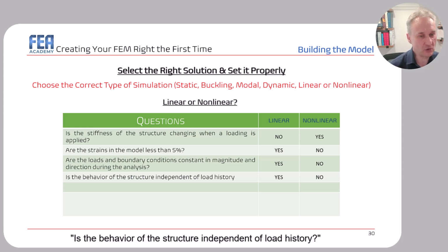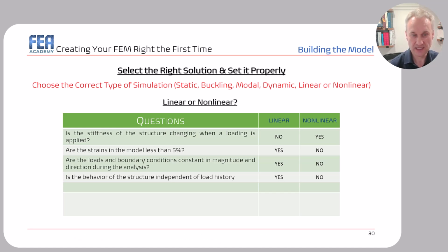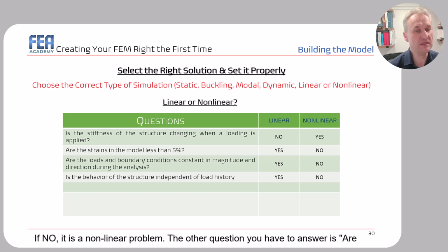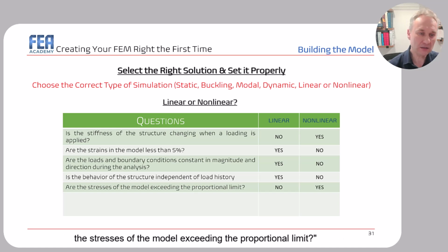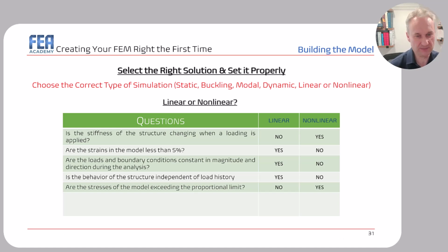Is the behavior of the structure independent of load history? If yes, it is a linear problem. If no, it's a nonlinear problem. The other question you have to answer is, are the stresses of the model exceeding the proportional limit? If the answer is no, it is a linear problem. If yes, it is a nonlinear one.